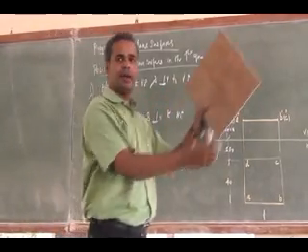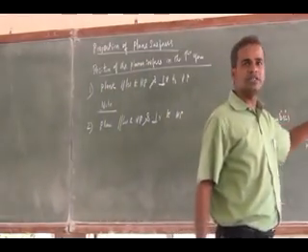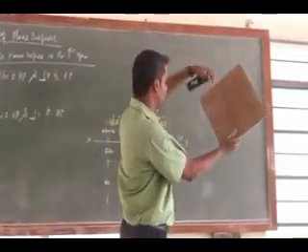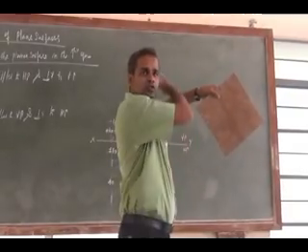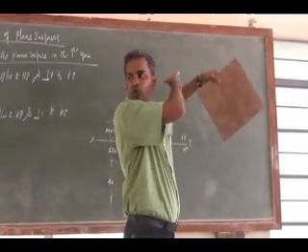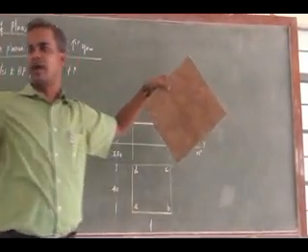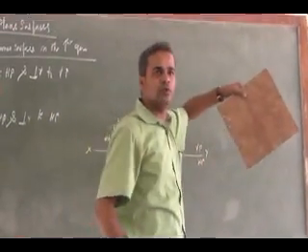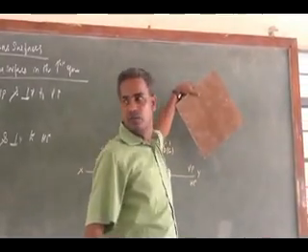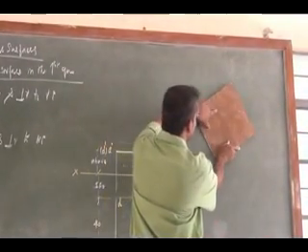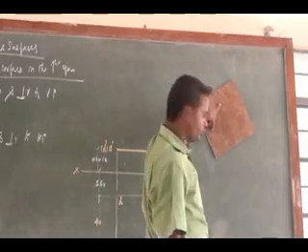You see, it is parallel. How am I going to proceed? So you know, it is parallel to VP, so the front view will have the true shape. As I told you, proceed with the problem by drawing the true shape as per the plane concept. Where I will have the true shape is here in the front view. Right. So I can move to the front view and draw the true shape.